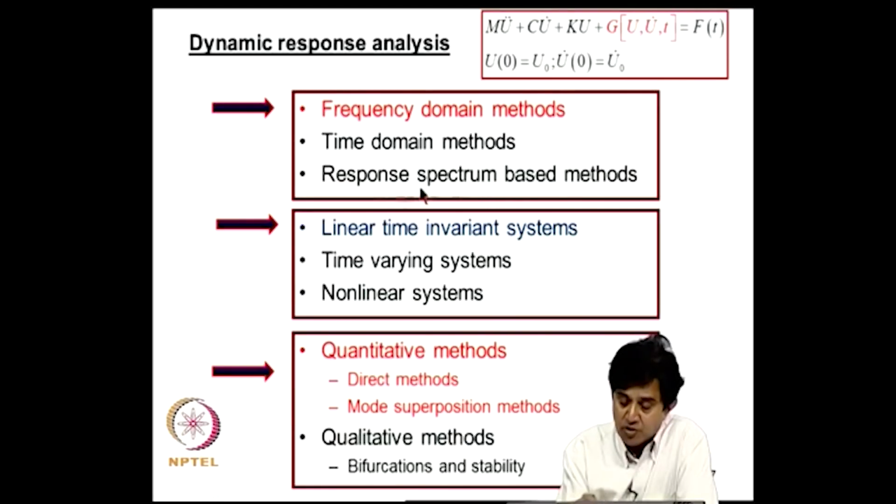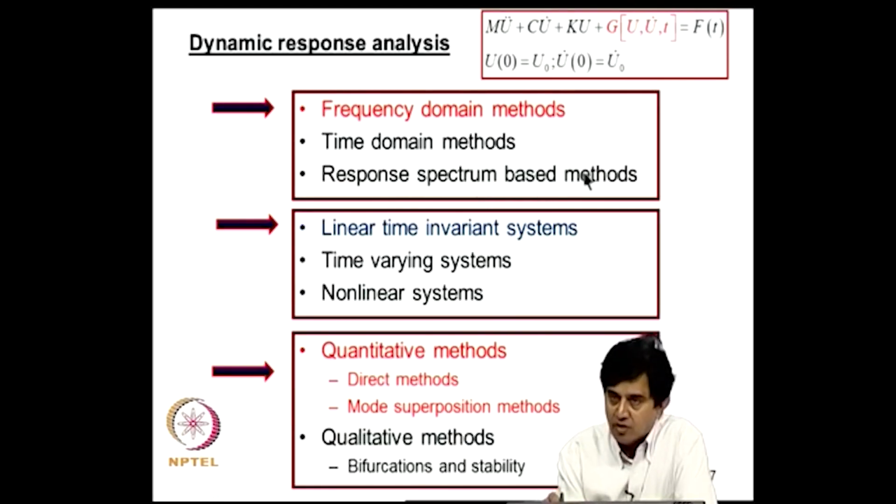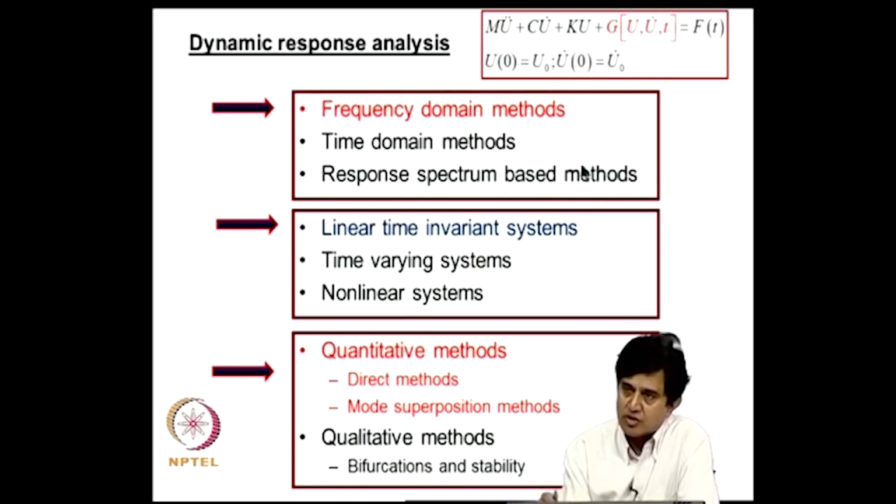The idea here in response spectrum based method is that part of the problem is solved in time domain and that solution is made available to the analyst in some form. The way the external actions are modeled is in terms of a set of response spectrum, and that would be the starting point, and by that time the time domain analysis would have been completed. So, the user of this method needs to do a free vibration analysis and construct the forced response. So, this classification is based on how you analyze the problem, either in frequency or time or a combined time and modal domains.